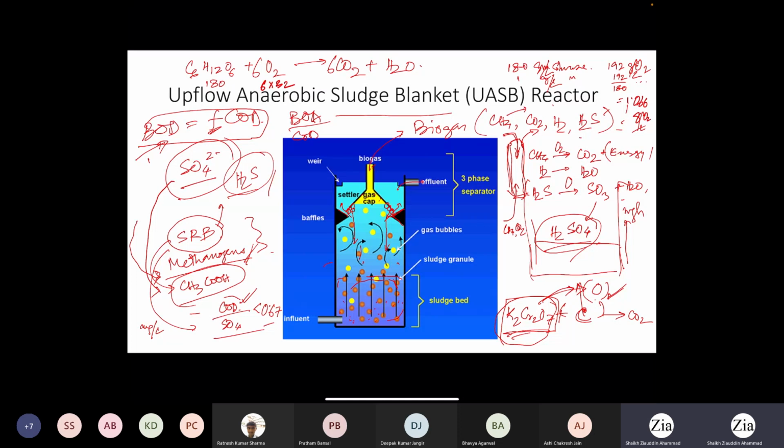But the only problem is these biofilm scrubbers or bioscrubbers are not very high rate systems. So you get much faster conversion in a chemical system than the biological scrubber. So one option is to add carbon to alter the COD sulfate ratio. Another option is to treat the gas obtained from the reactor. After getting the biogas, you just use a post-processing unit to scrub the gas, scrub the H2S.